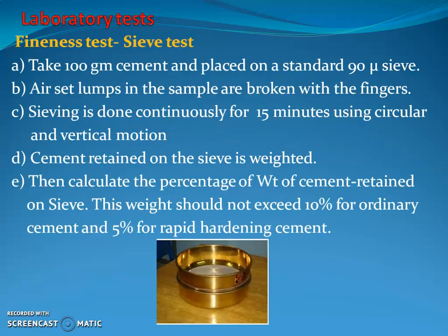Now let us discuss the different laboratory tests. First laboratory test is the fineness test. Under the fineness test category, first test is the sieve test. For sieve test, we have to use the 90 micron sieve.